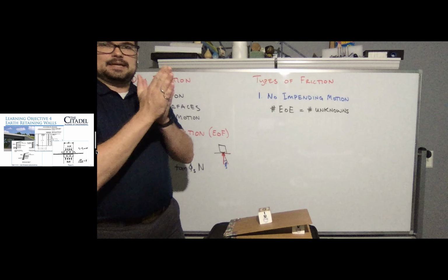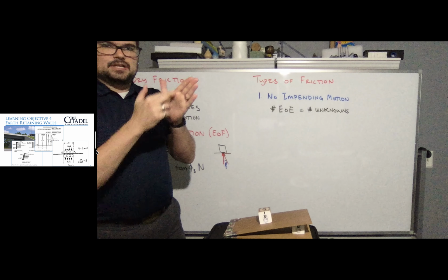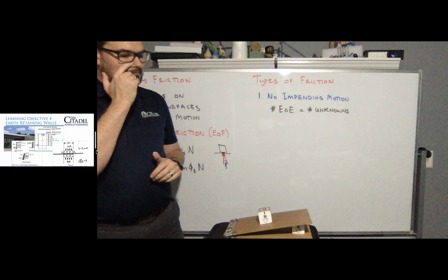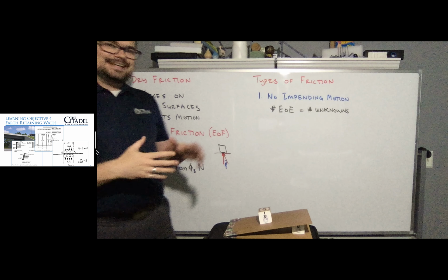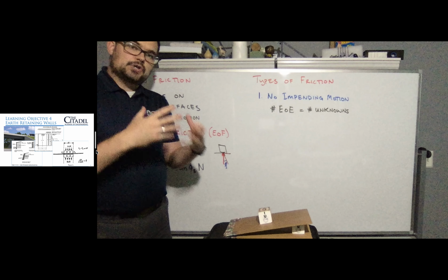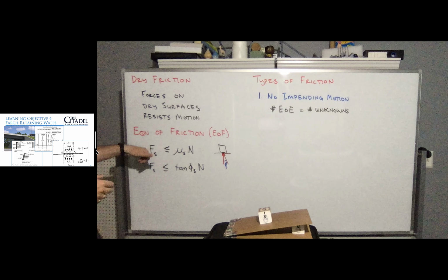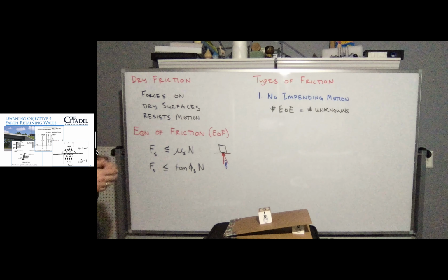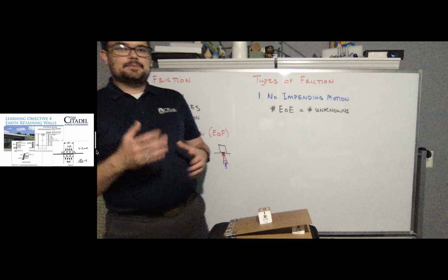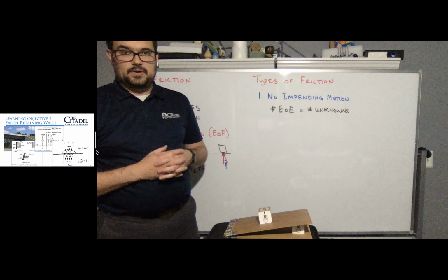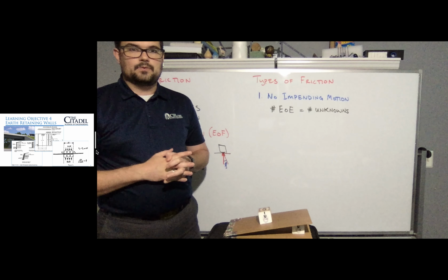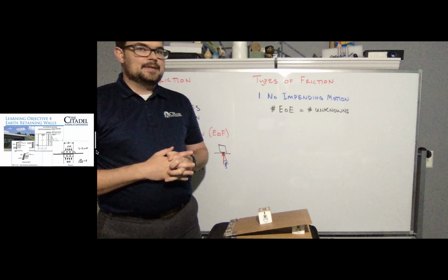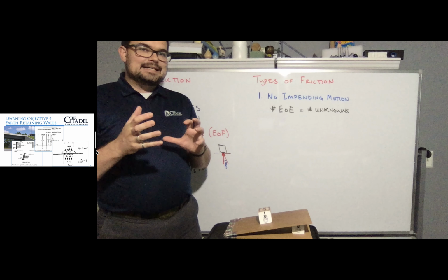So if you think about it, if you try to slide your hands, there's pressure at different points. But if you calculated the area, or the total force, the total normal force, the total frictional force, this relationship still holds. If you do a sum of the moments, you can figure out the centroidal location for that total frictional and normal force as it acts. And so those are some of the big ideas that are going on there.